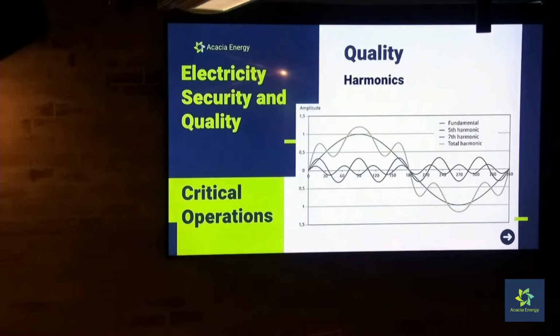Harmonic distortion causes heating losses in motors and therefore reduces their effective lifespan. It also introduces additional currents in all of your switchboards throughout the facility, meaning that you may see nuisance tripping of your circuit breakers, or you may need to increase the size or oversize your infrastructure to deal with these harmonics. On a lot of our newer sites where VSDs are far more prevalent than on our older sites, we're starting to see more and more issues with total harmonic distortion.